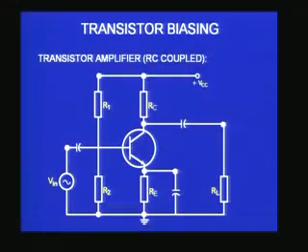Now let us move on to our transistor biasing circuit, which I now want to convert into an amplifier for amplifying an AC signal, alternating signal. So immediately you can see, if I want to do that, the circuit that you see on the screen is one such amplifier, which is called an RC coupled common emitter amplifier. You can immediately recognize several of the resistors on the transistor in the configuration, because we have just now seen that this is nothing but a voltage divider bias emitter biasing scheme. You have R1, R2 here, you have the RC, you have the RE, and you have the transistor.